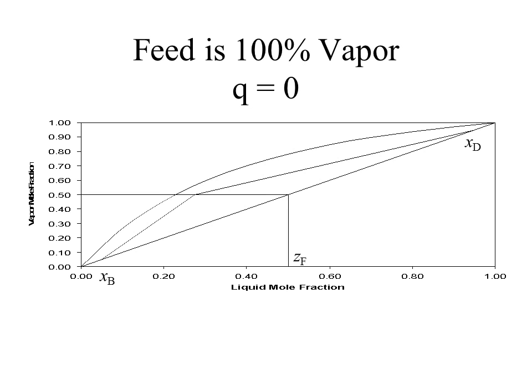We will then select our upper operating line, which intersects the y equals x line at xd, and then we can choose the slope whatever we wish, but it will point where it intersects the Q line. That point we would then draw from the Q line down to the y equals x curve at xb. Now we're ready to determine the number of stages.